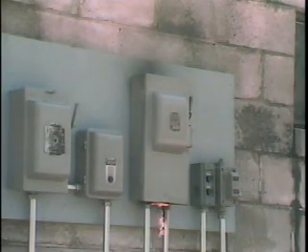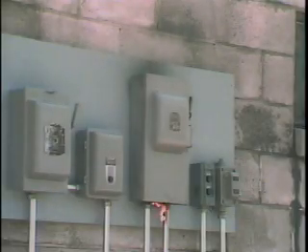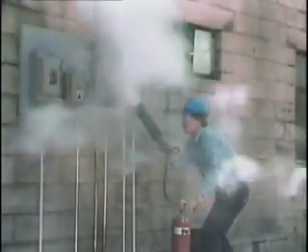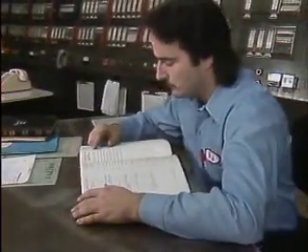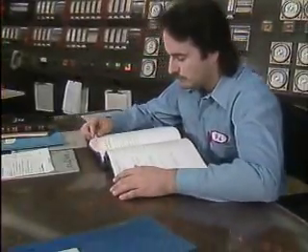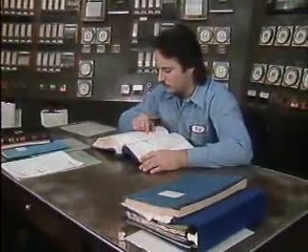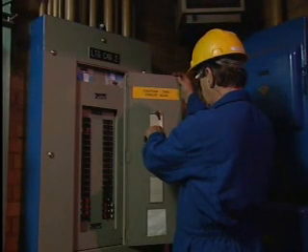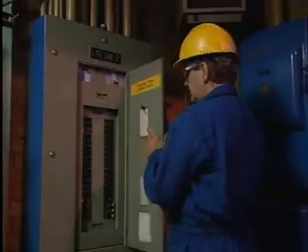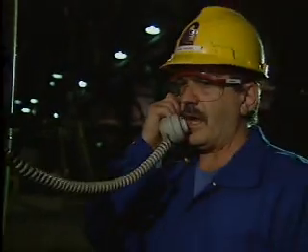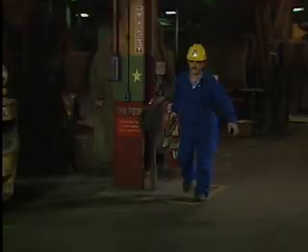Another type of emergency situation that you may face is an electrical fire. Most facilities have special training requirements for fighting fires. You need to know and follow your company's specific guidelines at all times, but there are some general guidelines for firefighting. One of the first things that should be done is to cut power to the area of the fire if possible. Another thing that should be done is to report the fire. After these two actions are taken, an attempt may be made to put out the fire.